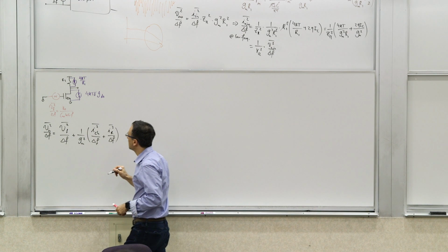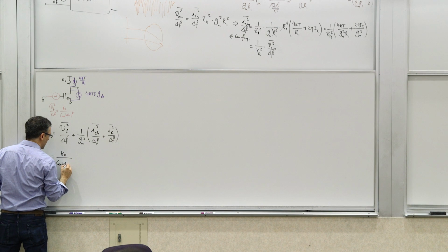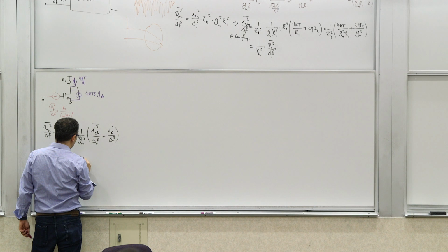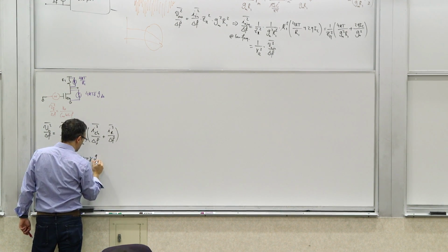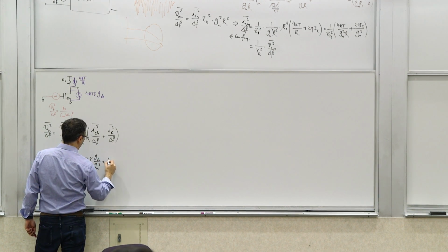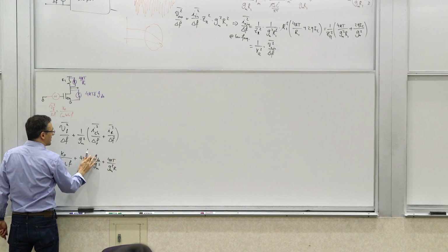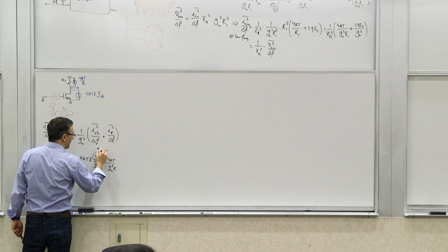You can plug in values in there. So you get KF over Cox WLF plus this thing, which basically gets you 4 kT gamma GD0 over GM squared plus 4 kT over GM squared R. And yes, only for a non-velocity saturated device, this becomes GM, so this becomes 1 over GM.